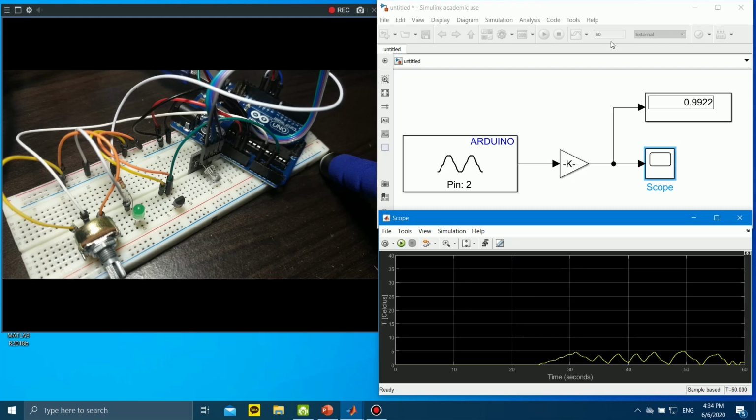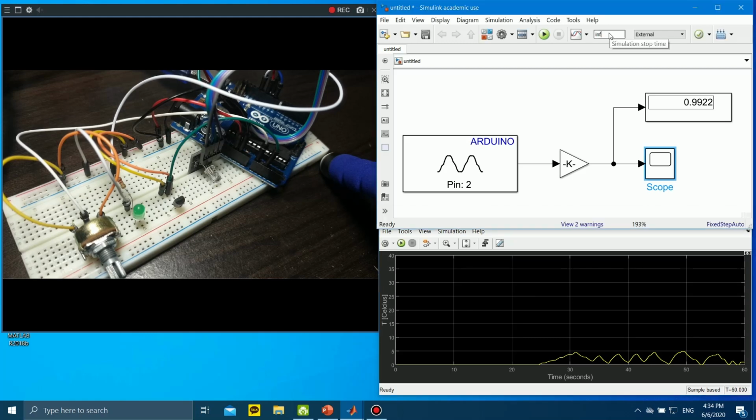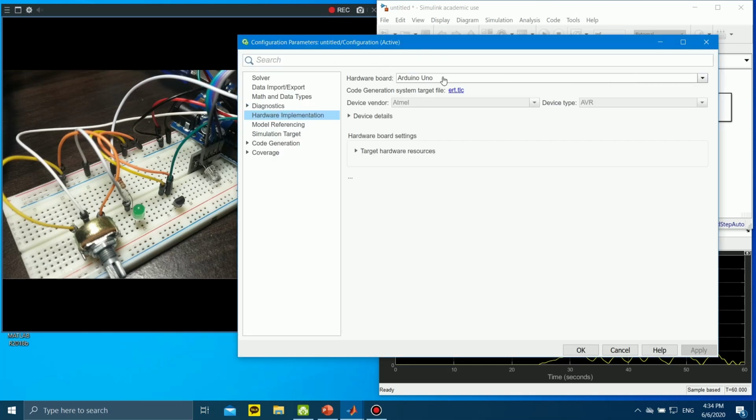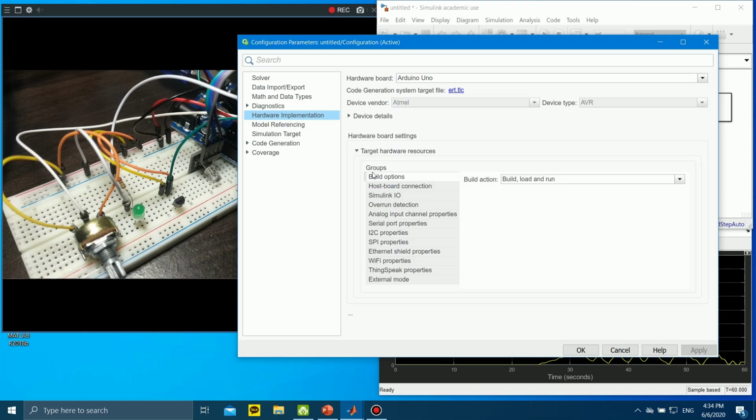And we will run this for infinite and select external device. We don't upload this to Arduino using run, but use deploy instead. And make sure the connection is Arduino Uno, and the target, of course, is COM. You can set it here. My device is connected to COM5.